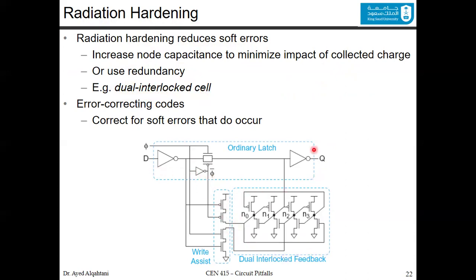So this is an ordinary latch. And now, just before the inverter, notice that we are protecting the D, and we are also protecting the Q from any outside connections. So when you fan out here, this inverter will protect the remainder of the cell. Similarly, this inverter protects the remainder of the cell from any other inputs as they fan in.